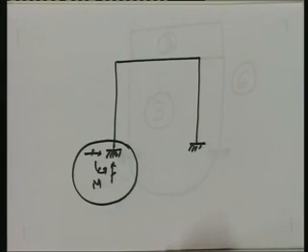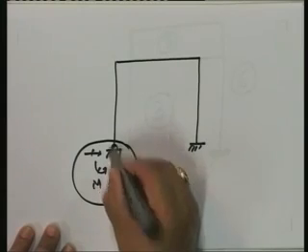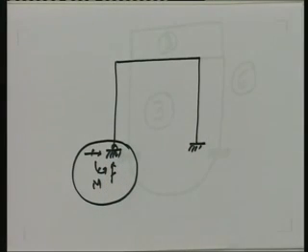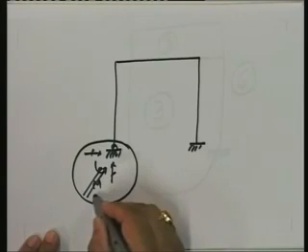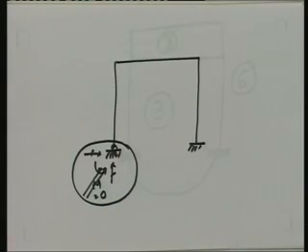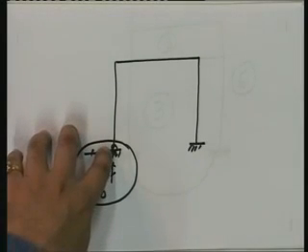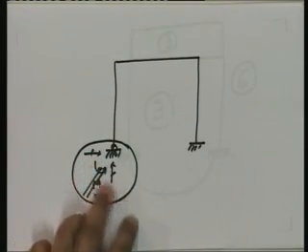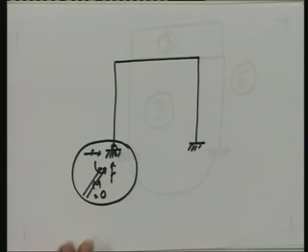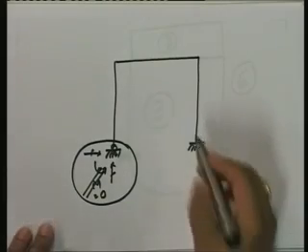Let me now say that what I am going to do is, I am going to release the restraint against rotation. What happens? When I release the restraint against rotation, M has to disappear, because M has to be 0. So as soon as I have taken a fixed end and released its rotational capability, what does it become? It becomes exactly the same as a hinge support. Let me do something more. So let me do the same thing over here.